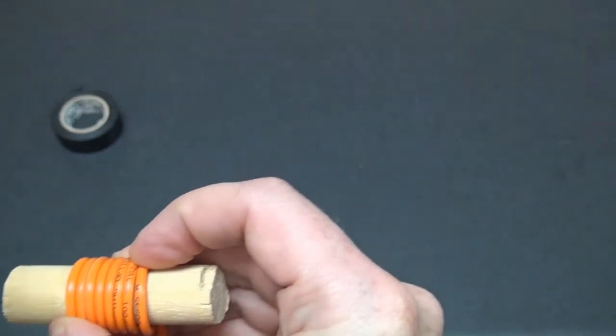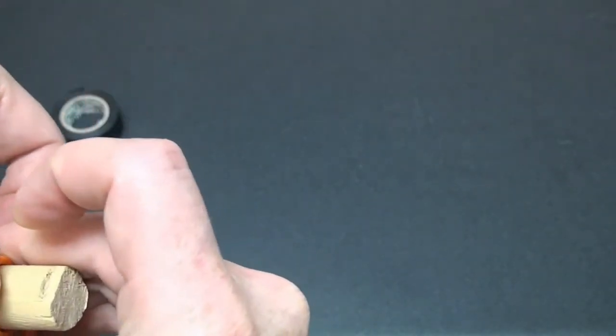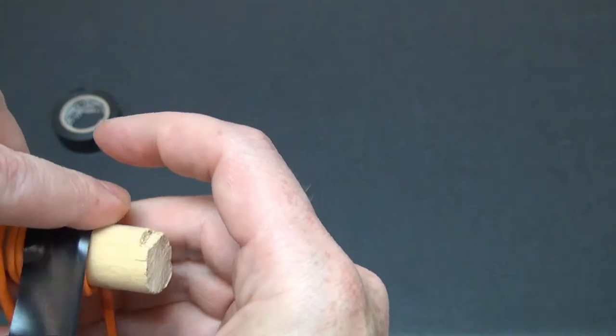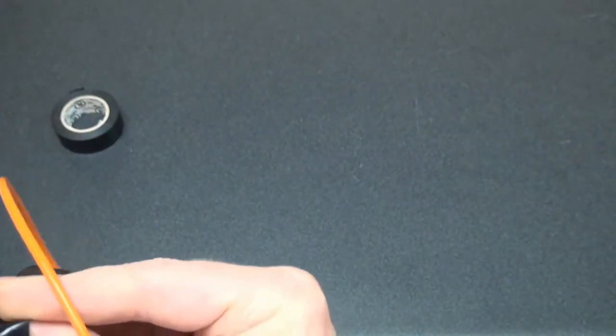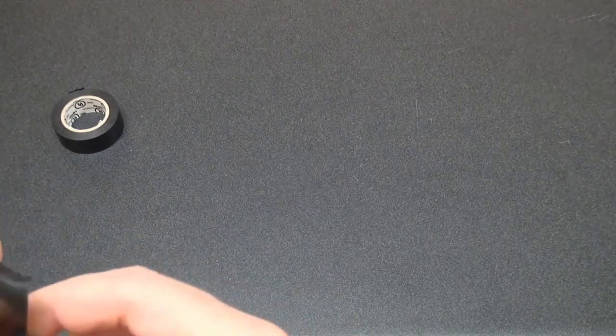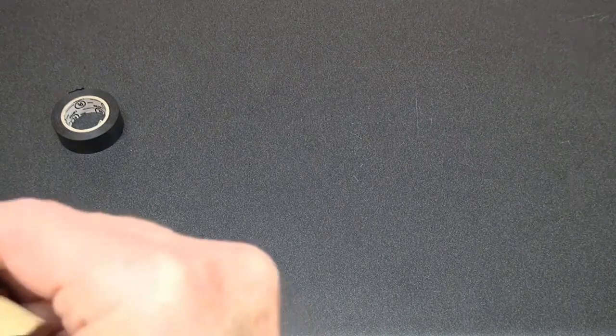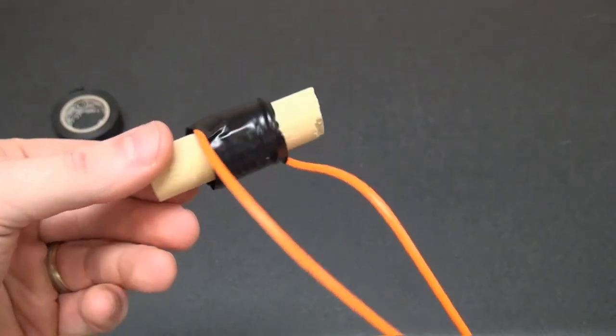So holding the patch cable in this position, simply cut off a section of electrician's tape and begin securing the patch cable to the mandrel. Now, the reason we want to make sure that we secure the patch cable around the mandrel is that once the cable is wrapped around the mandrel, if you let it unwrap, this will change the reference level as you're doing your testing. So we want to make sure that we have this electrician's tape nice and snug so that the patch cable is fully wrapped around the mandrel and it doesn't come unwrapped.